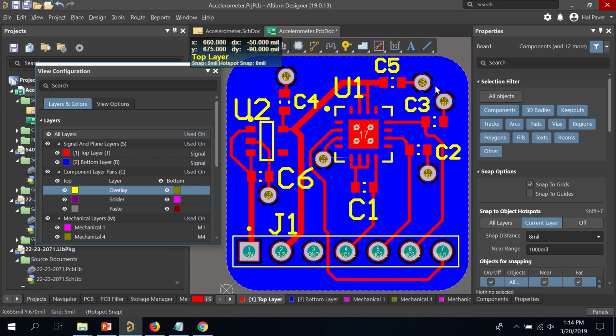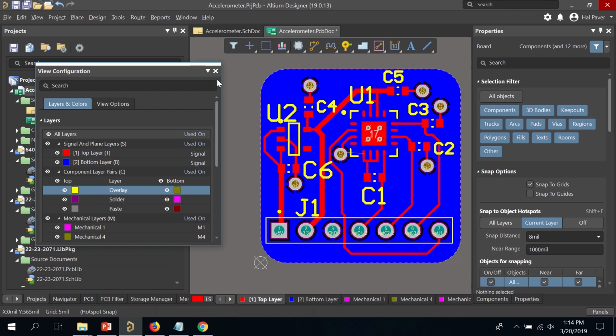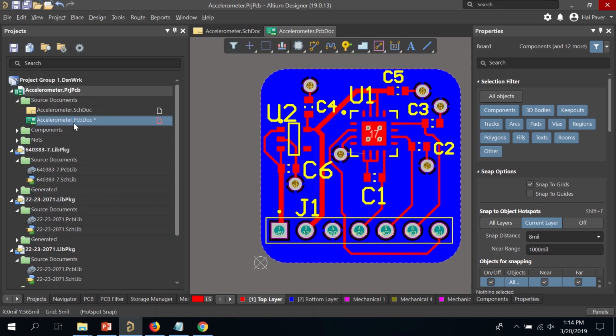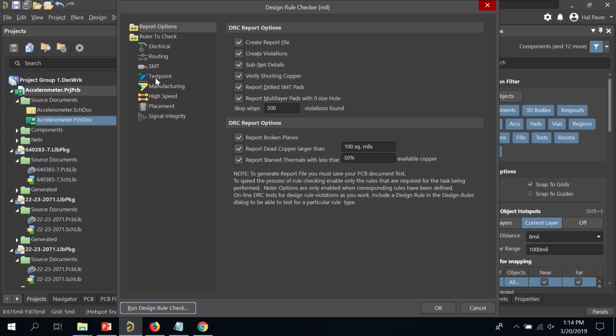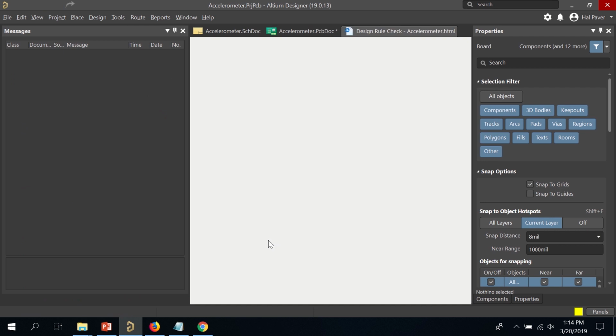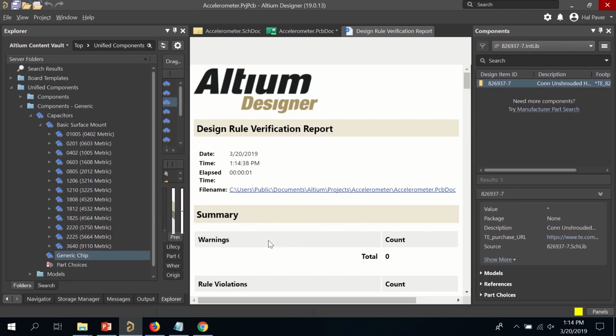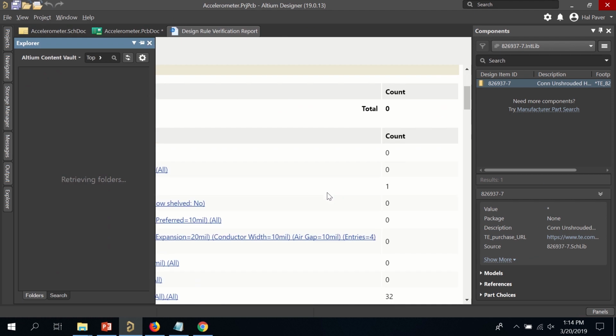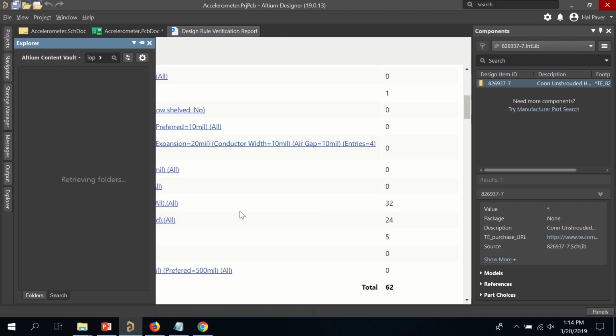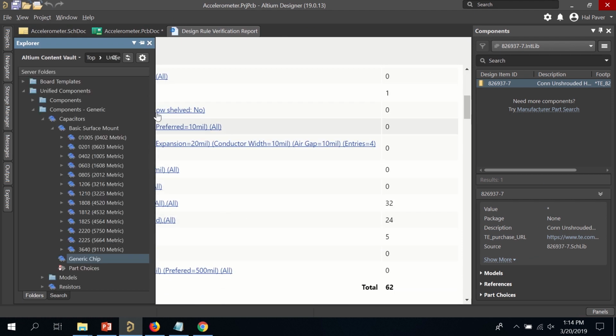Okay, so at this point we're done with the layout. Make sure that you save everything. And now you do the design rules check where you find out that you're not really done. So go to Tools, Design Rules Check, and it's going to check the default options except for the option that we changed. And you'll go through the errors and see which errors you think are actual errors and which errors you think are okay. So I have errors in 3 classes.